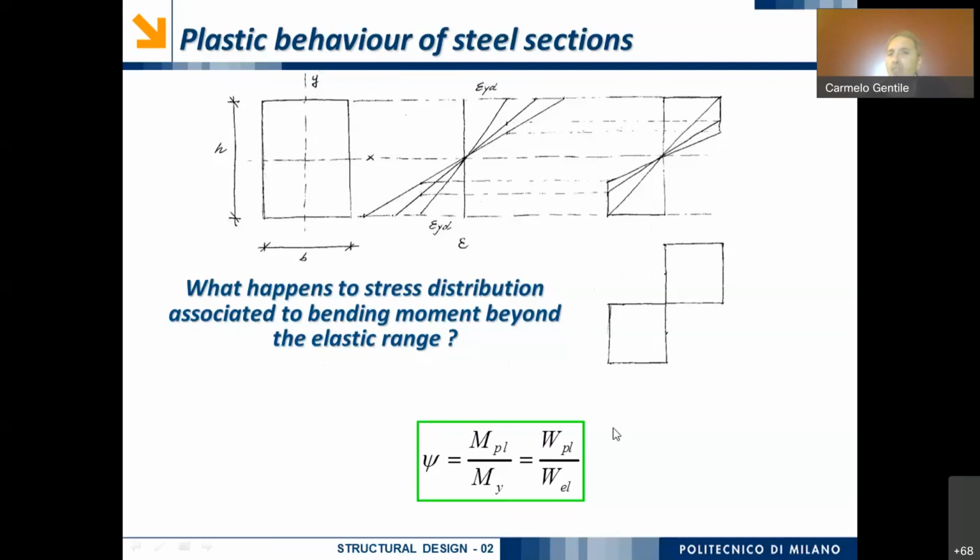But we can also observe from real I-beams, as you can see in the exercises I've sent to you, but also in the exercise that Dr. Ruccolo will perform in the second part of the class of today, you can easily verify that the plastic ratio in I-beams is in the order of 1.1, 1.15, 1.05. It is larger than 1, of course, because the fully plastic moment is larger than the yielding moment, but it's not so large, okay?